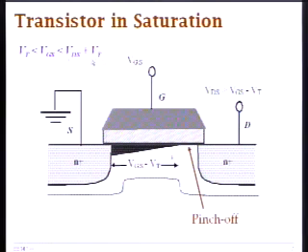And the way you identify if the transistor is in saturation is that you need to observe the relationships between voltage values at different transistor terminals. So the transistor has to be obviously turned on, so VGS has to be greater than VT, and also VDS has to be greater than VGS minus VT, or equivalently VGS is less than VDS plus VT in one compact formula. So that's your transistor in saturation. That's a very important mode of operation to understand.